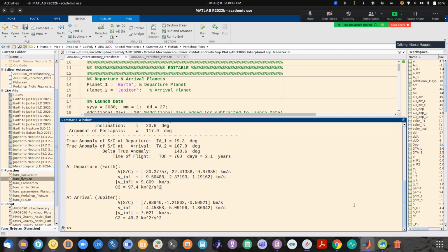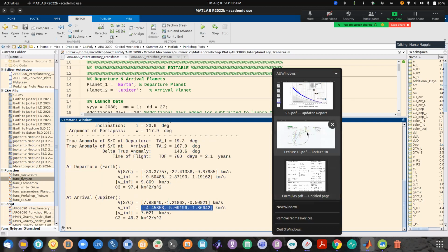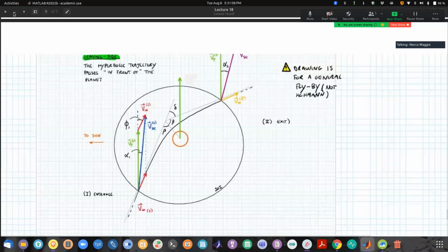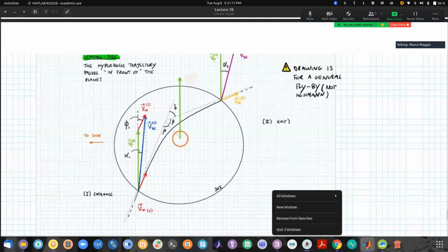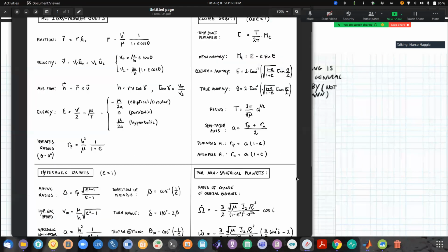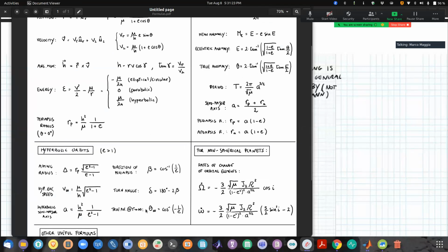Moreover, you have to verify that things are actually possible at flyby. What you have with the two legs are the v infinities. So here at Jupiter, you have the vector, the v infinity at the entrance of the sphere of influence. And once you compute the second leg, you have the vector with its three components at the exit. Now, you have two vectors, so you can easily calculate the angle between these two vectors, and the angle between the two v infinities at the entrance and at the exit of the sphere of influence corresponds to the turn angle.